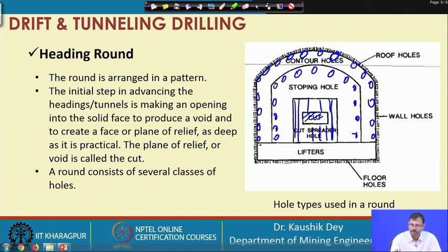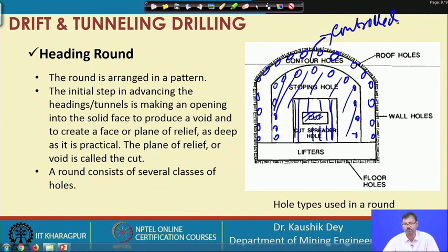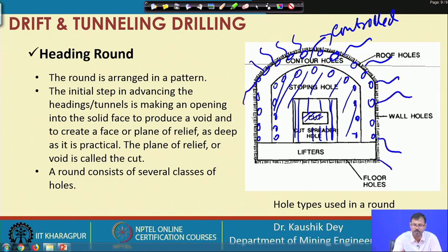So, the production has to be carried out up to this, similar in fashion to the surface blasting. Then cautious blasting, controlled blasting or controlled excavation has to be carried out in the periphery part, so that the damages will not occur in the remaining underground rock mass, which would increase the support cost.